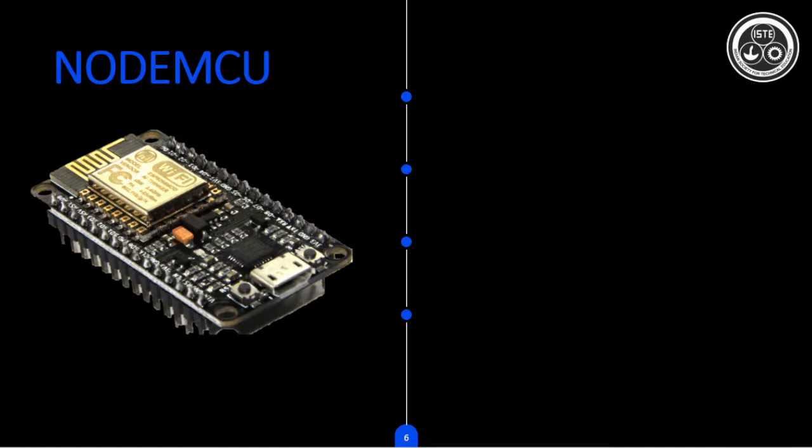This NodeMCU is not a microcontroller board, it is a development board. So this development board contains an ESP8266 SoC with it and breakout pins to connect several sensors, to connect several things, and we can interface it with several other data or sensors or anything. And it has a micro USB female port. We can program using that, or else we can read the data using that pin. And there are two switches, one is flash and one is reset. We will be using reset switch a lot, and there are some pins.